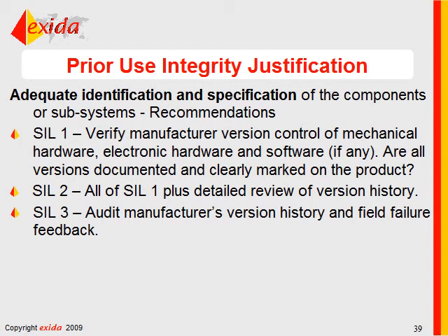Oh, I see a question. Let me check. The question is, can the vendor do the proven in use, or must it be done by the end user? Yes, and the answer is, it's a common interpretation that prior use justification must be done by the end user.